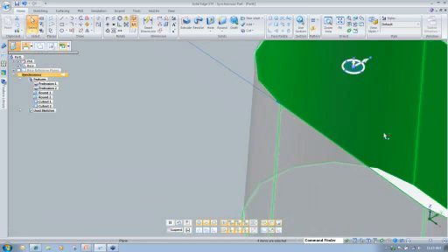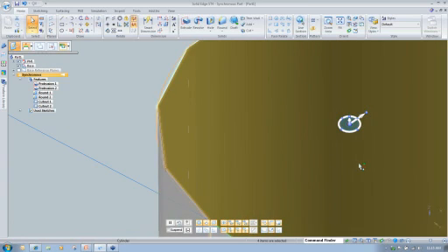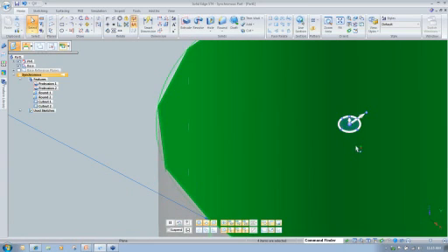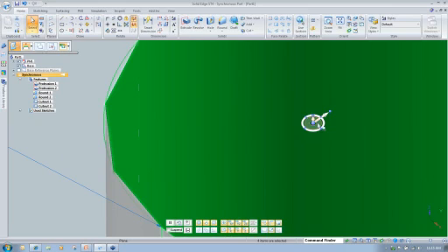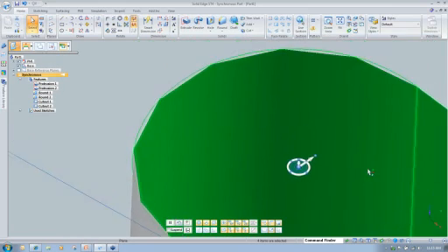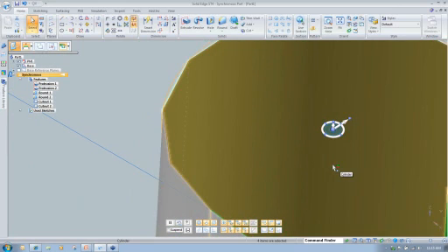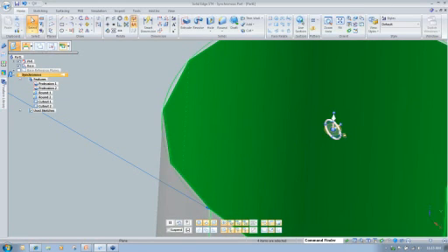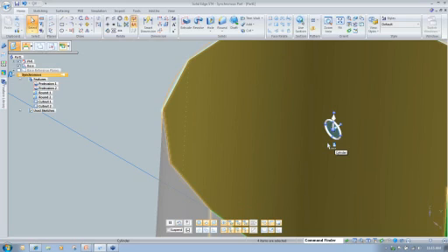and you can see that right now the primary axis is tied to one of those, and then your origin in the center, and we have the tool plane. Now one thing I want to tell you about the tool plane is that's what allows you to change the direction of your steering wheel. Another tip and trick for you, by holding your shift key and selecting that plane, you can flip that direction. And what it does is it reverses the secondary and primary axes and allows you to go in different directions. In this case, we're going to keep going in that direction.